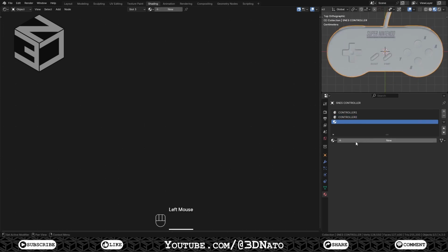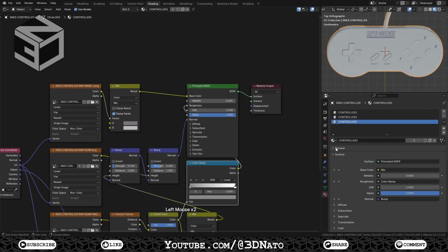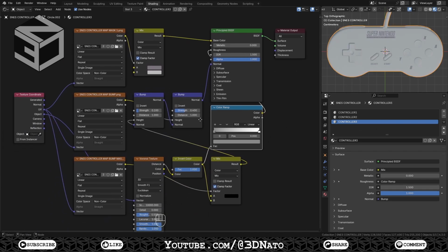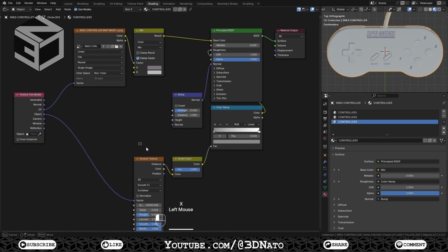Press the plus sign to add a new material. Select the Controller 1 from the list, click this 2 to make it unique, and rename it Controller 3. Go to Edit Mode, select these faces, click Assign, and exit Edit Mode. Delete both bump maps, the first bump node, and the second mix color node.